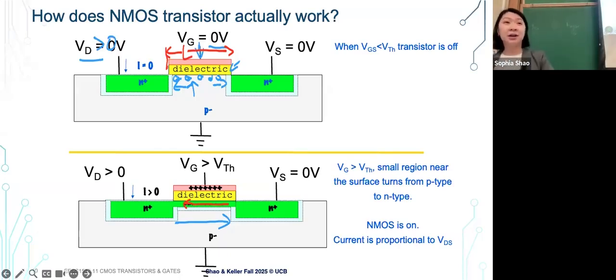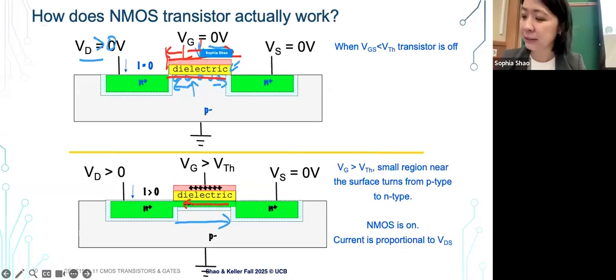And I guess we talked about resistors. How about capacitance? How does the gate length impact the capacitance of the transistor? It's going up, right? You have a bigger area now, so you can attract more charges. So you can really think of this as just a capacitor here. And by applying, again, what we discussed, voltage here, we can form a channel, and then that becomes the resistor we talked about, right?